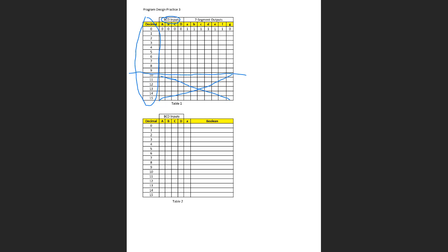And then, since you have these BCD inputs, over here are those LEDs. You remember those LEDs were each denoted by a letter from the alphabet. So you got LED A, LED B, C, all the way through G. Well, what would it take to make a decimal 0? When I say what will it take, which segments of the 7-segment display would I have to light up in order to display 0?